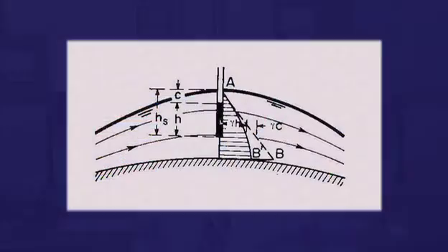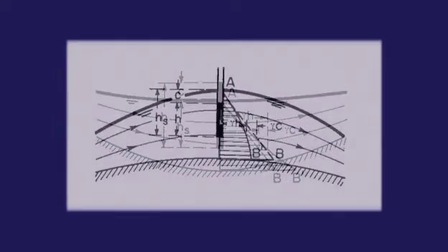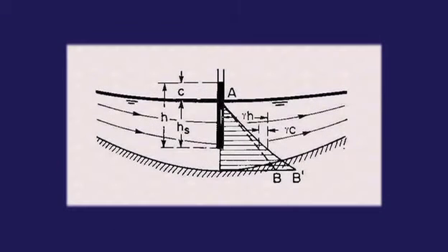Uniform flow is essentially parallel flow. Gradually varied flow may be approximated as parallel flow. Under curvilinear flow, the pressure distribution is not hydrostatic. Curvilinear flow can be either 1. Convex or 2. Concave. Under convex curvilinear flow, the pressure distribution is less than hydrostatic. Under concave curvilinear flow, the pressure distribution is in excess of hydrostatic.